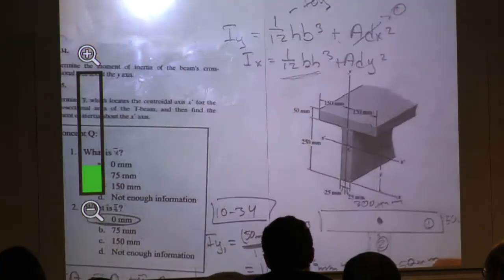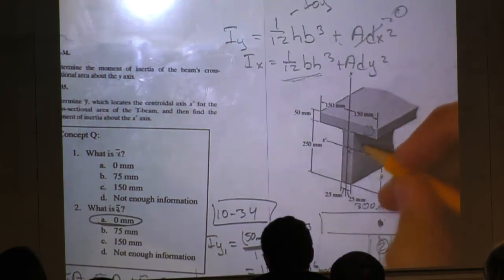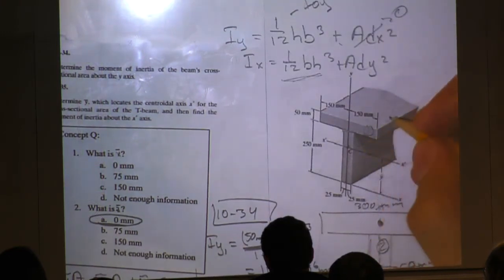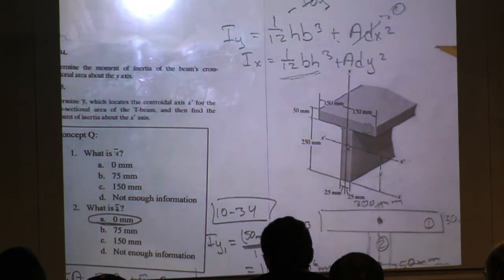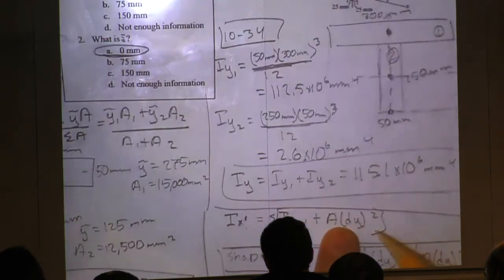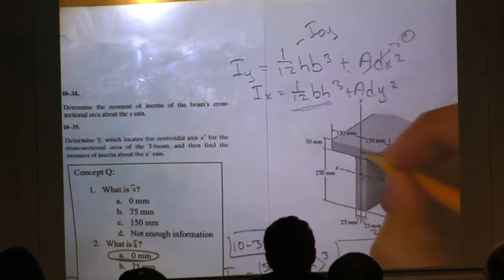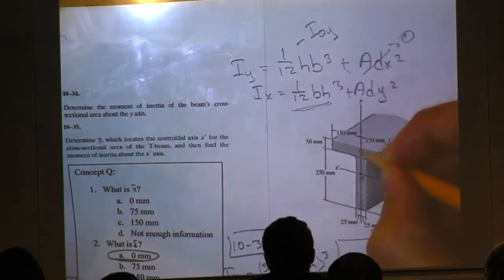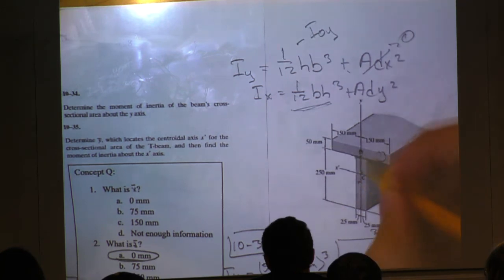So there is a difference between our centroids here, or is there? I wrote it, but I'm not sure that there is. Okay, so we need some dy, right? So we need some distance in the y-axis. So it's some height. So our y centroid for this shape we know is here, and our y centroid for this shape is about here. So this is the distance that we're finding. That's our dy value, right?